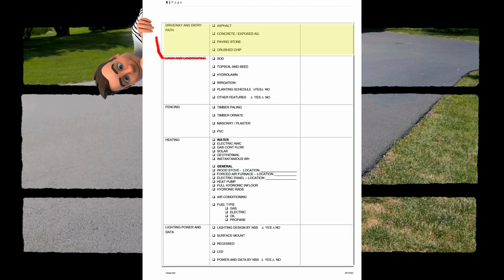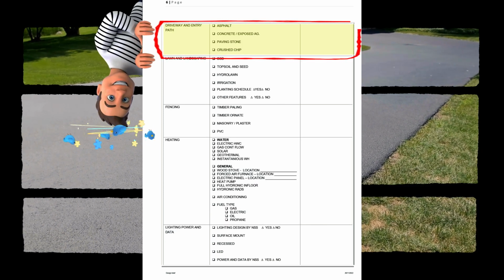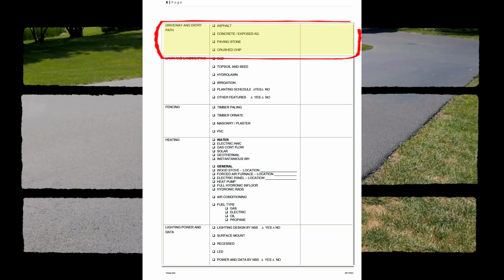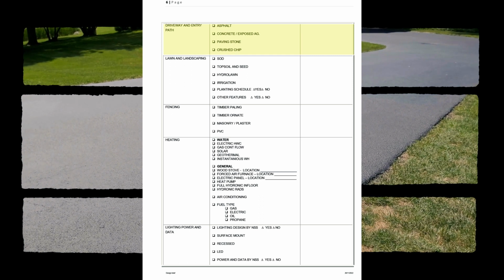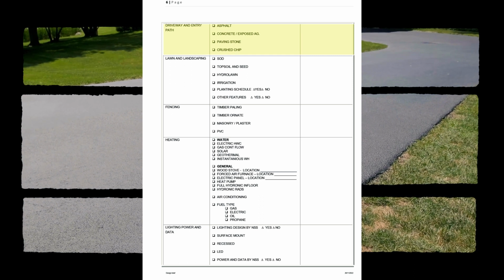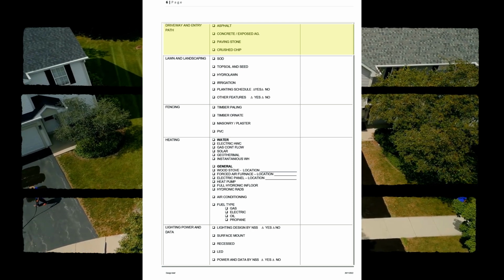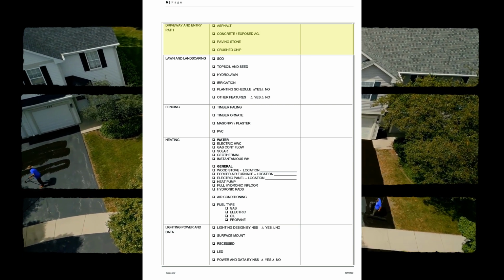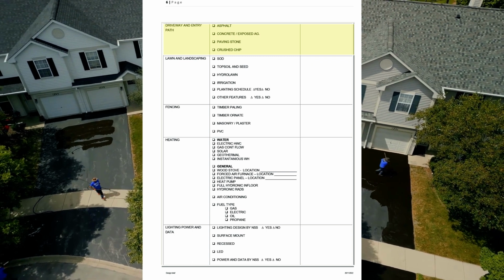We then move on to exterior walkways and driveways. The location and desired material should be documented. Particular attention should be paid to driveways on sites that are steep, as the location of driveways may warrant the need for cut and fill earthworks and retaining walls. The location of driveways is also regulated by most municipalities. You should familiarize yourself with these regulations.